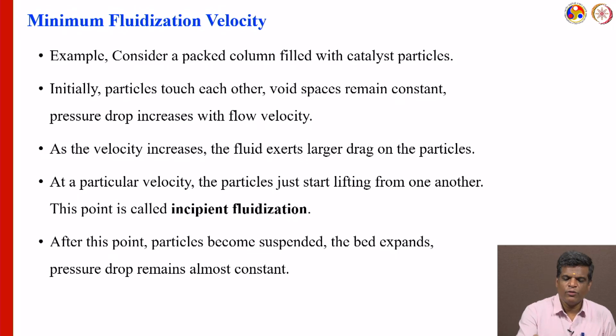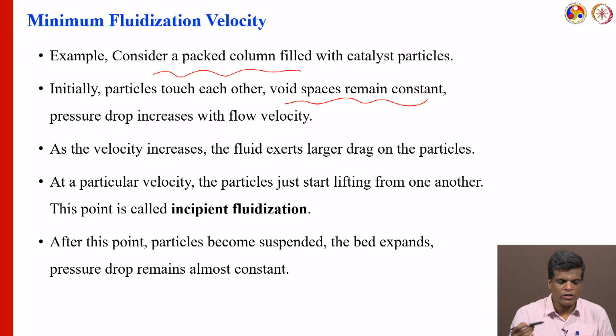For example, consider a packed bed column filled with catalyst particles. Initially the particles touch each other, and the void spaces remain constant when the flow starts. The pressure drop also increases with the flow velocity. When the flow starts, the pressure drop definitely increases, because the fluid is flowing through the packed bed. So, the pressure difference will definitely increase.